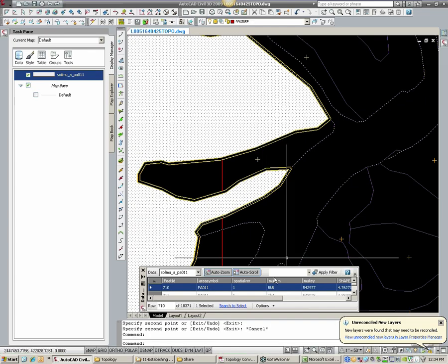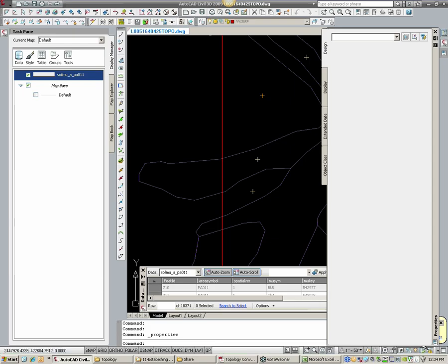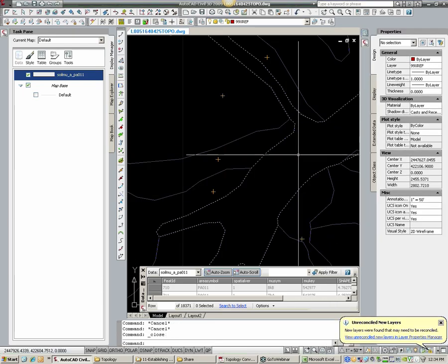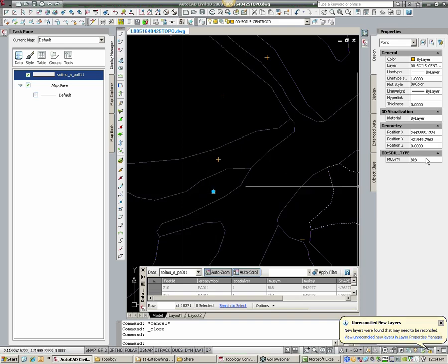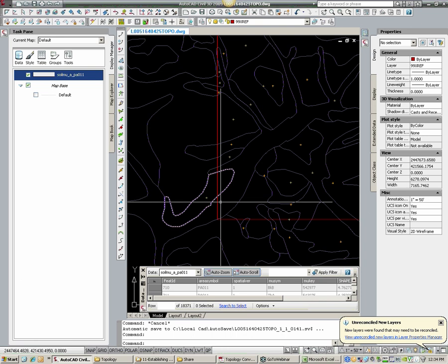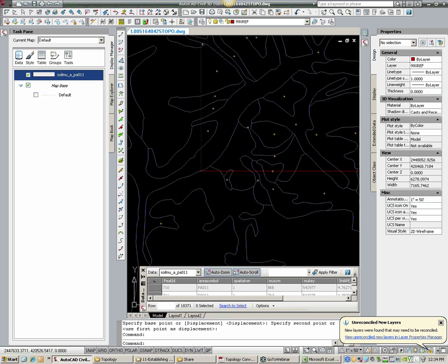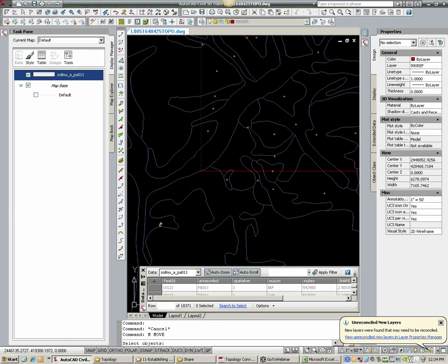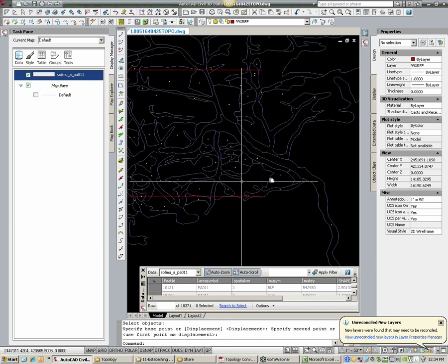And I can also verify, like, okay, that says BKB. All right, well, let's pull my AutoCAD properties dialog. Let's lock this open. And when I click on the little node object out here, that says BKB as well. Okay, well, that's good. That's important that they match. I can bring this up here as well. You can see this is a big old long one, and actually the node formed all the way down here. So we'll bring that up, and so on and so forth.